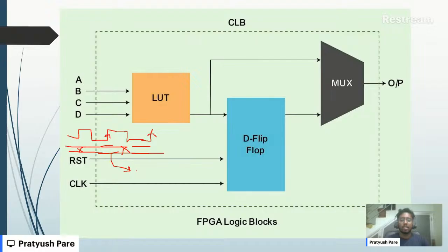You need a storage element which can store the output of this across the cycles, so that if there is a dependency for some element in the next clock cycle, this can be used as a memory element. So this will be just a one clock cycle delayed version of this signal. Consider it as an output O. The D flip-flop output will be stable until the next clock cycle. Got it?